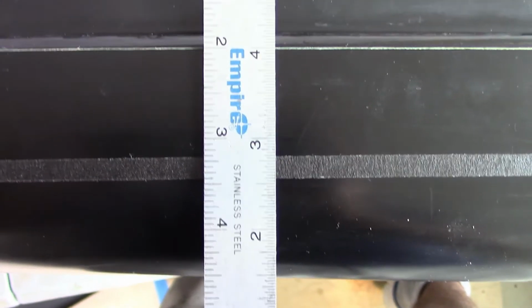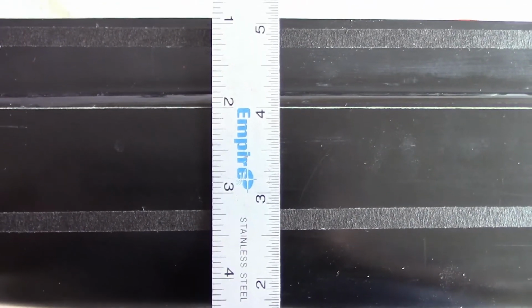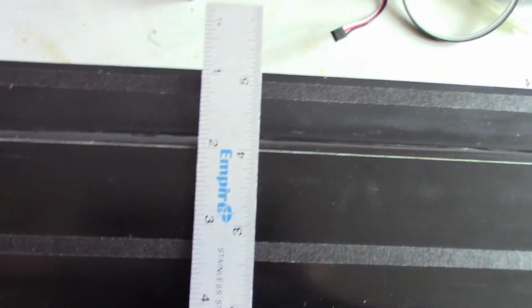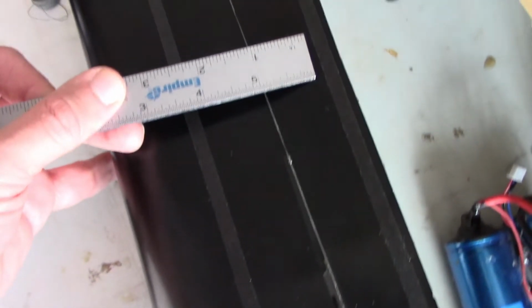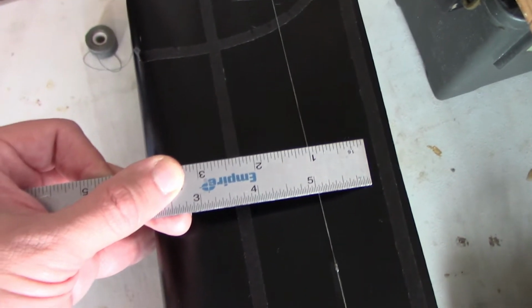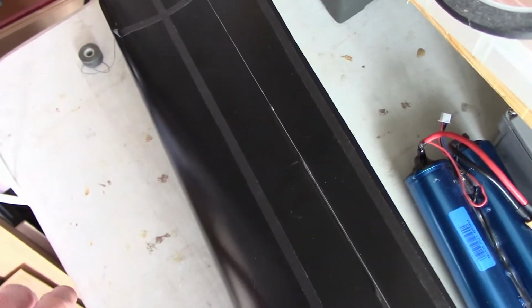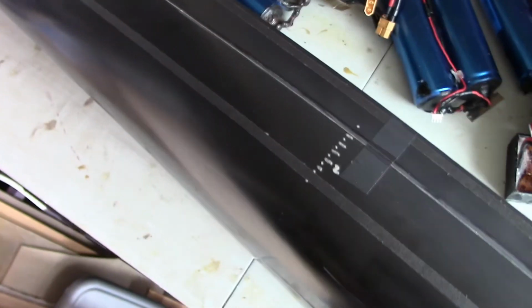You can kind of see there, I actually ended up going 1 3/16 down most of the length of the hull, so that gives me about a 1/16 of buffer. Then up in the bow I went closer to 1 1/4, because the bow is kind of at the extreme end. If I ended up wanting to get the stern down a little bit lower, then the bow is going to come up, so that'll give me a little bit more buffer there.